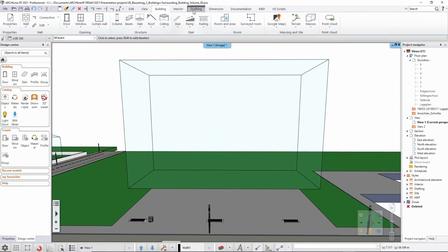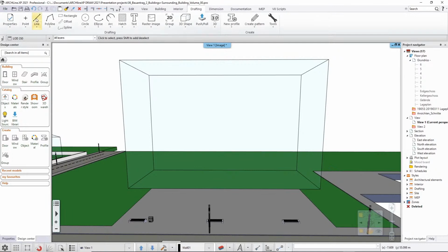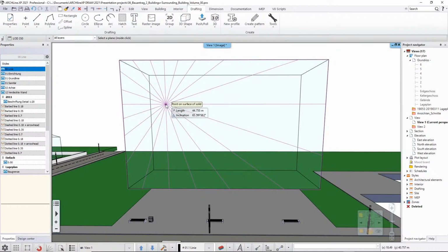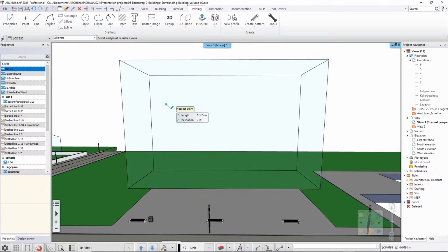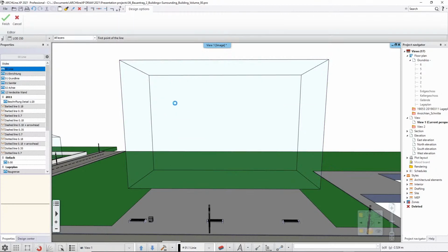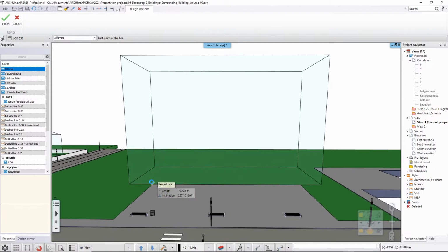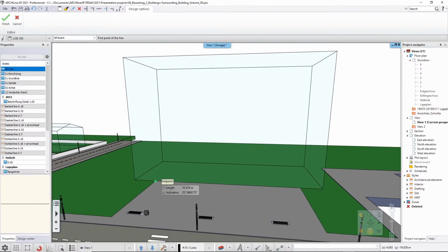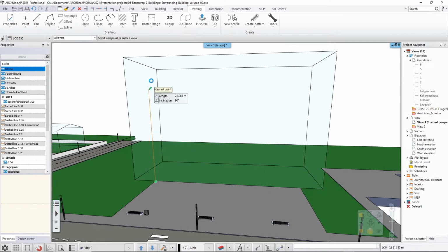And then when you start drafting, you can click on the line tool, for example, and then select the surface, which in this case is the one facing towards me. Instead of starting my line anywhere here, I will find this corner point, click once and start drafting on this surface. Once I hit the proper height, I can also hold the shift key to lock the direction and then refer to this other corner point.